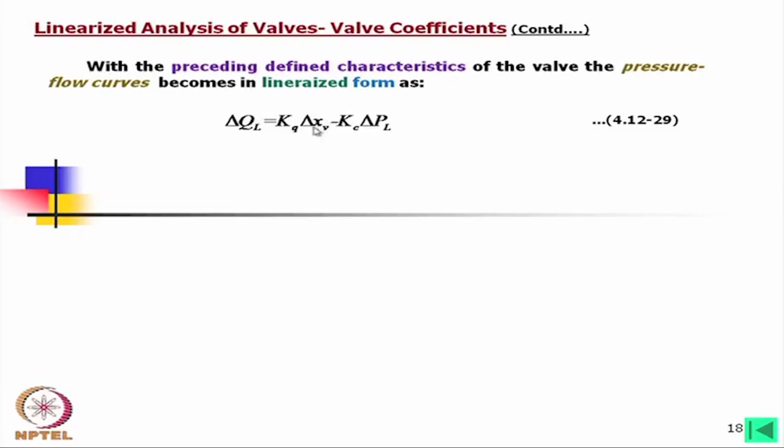If we can give this much displacement, then automatically this will be adjusted. So, this is the control feature of these spool valves. Now, you see these actual equations are nonlinear and complicated, but we have arrived at the simple form, and if these two coefficients are known, then we can do it.